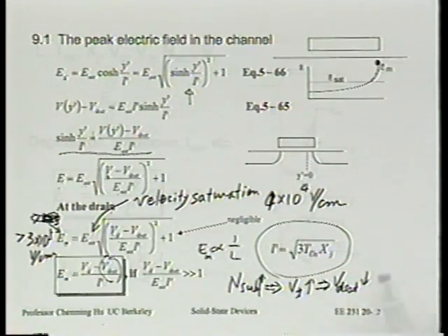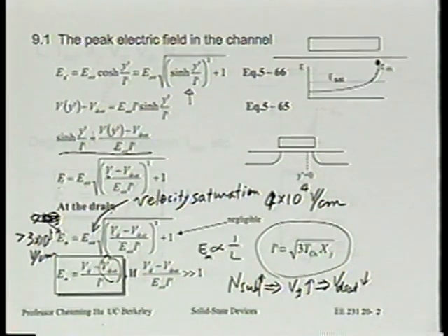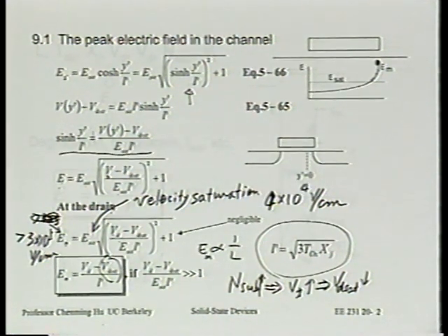But what this model is telling us, and that usually surprises people, is that the doping concentration is not as strong an effect as one may think. Because a lot of people like to think about what happens in the pinch-off region like a one-dimensional p-n junction. For example, they like to use a one-dimensional p-n junction's depletion region width to model the channel length modulation. Okay, we've already seen how different the problem is from a one-dimensional p-n junction.